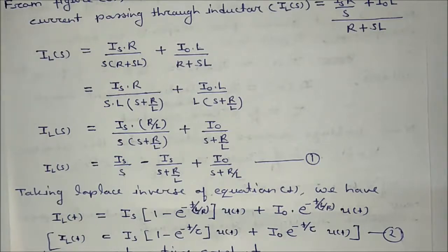it has been discussed already that the total response in the circuit is always equal to the forced response plus natural response. Okay, and the natural response is calculated only for what? Initial conditions. That means the external applied input must be 0 to get the natural response of the network.